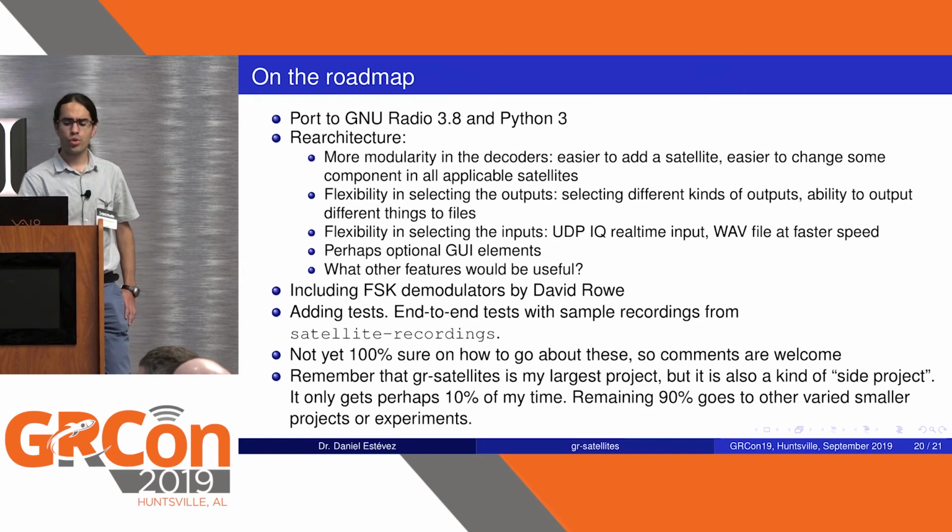I would also like to try adding some FSK demodulators by David Rowe. These work on the IQ signal rather than on the FM demodulated signal, and by doing so can achieve better performance by filtering the different side lobes of the FSK signal.